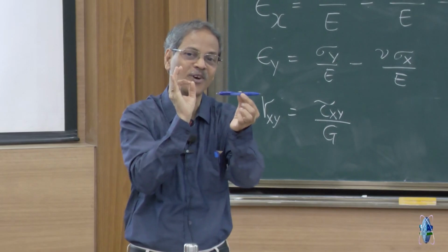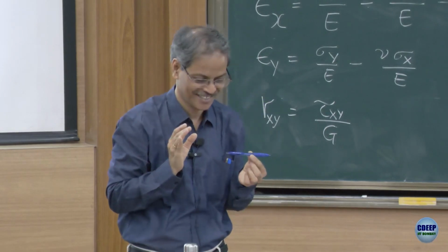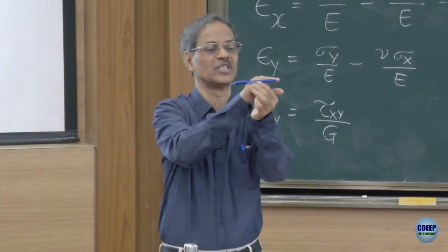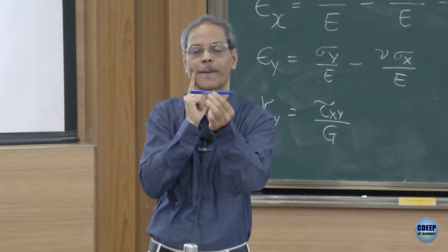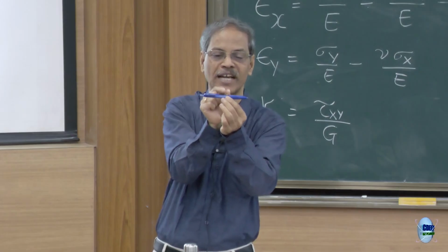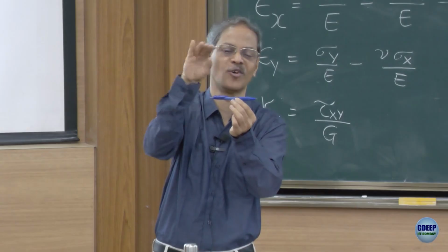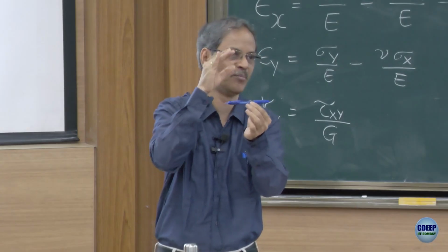Now think in terms of what happens if I extend this to two dimensions. What I did here was to take the entire domain into bits and pieces, and over each piece, each element, I have a linear variation of unknown variable or a quadratic variation or whatever, cubic variation if it was a beam element.